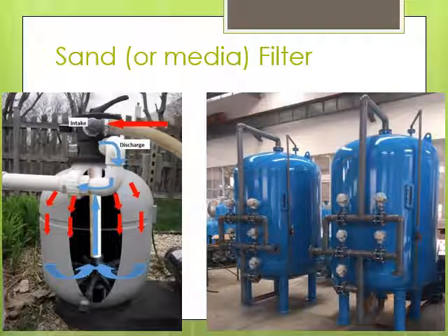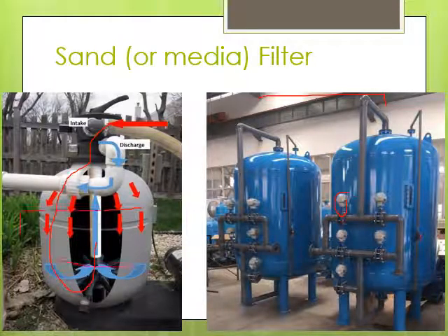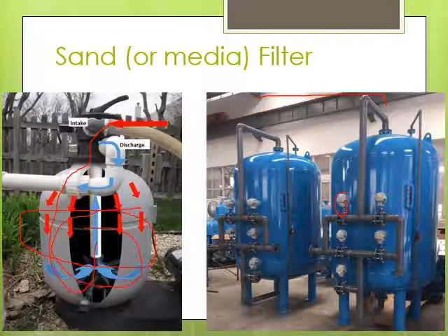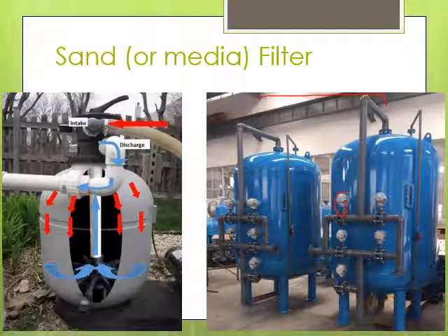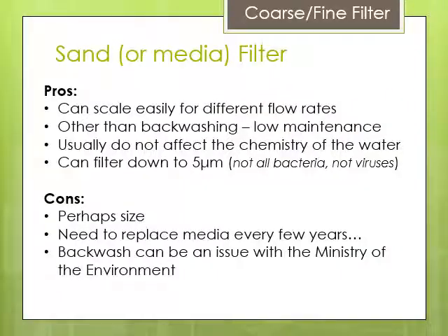There's another on the right. This is a commercial greenhouse configuration. These are the sand filters, and these are the various valves for whether you're backwashing or actually filtering. And then here's a pool system showing you how it works. Normally this is two-thirds full of sand. I just made a real mess of it. So you fill the thing up to about this crease here, all full of sand, and that's your filter media. And sand will last for quite a long time.